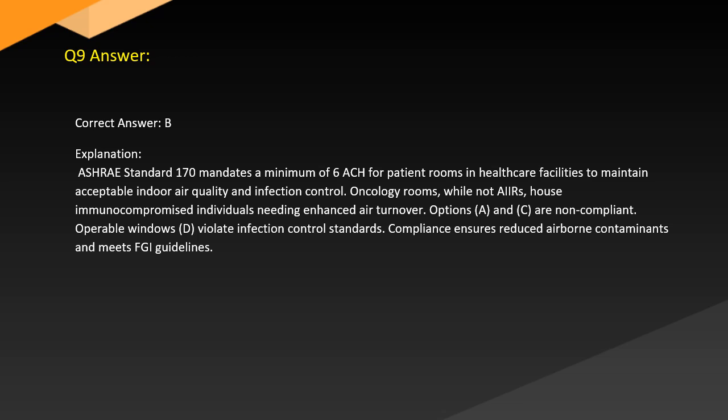Answer. Correct answer: B. Explanation. ASHRAE Standard 170 mandates a minimum of 6 ACH for patient rooms in healthcare facilities to maintain acceptable indoor air quality and infection control. Oncology rooms house immunocompromised individuals needing enhanced air turnover.